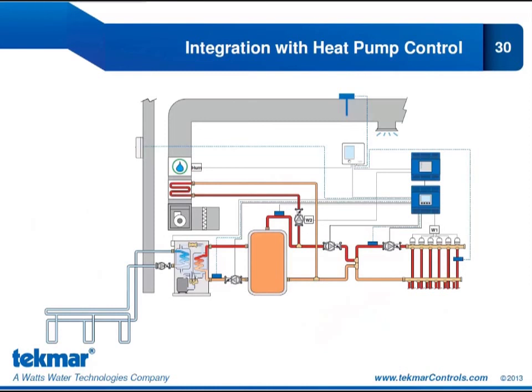Here's how the thermostat 557 might integrate with our house control 406 for an overall geothermal system. You can see here we have radiant floor, and that would be our first stage of heat. And it would also provide radiant floor cooling if we chose to design for that as well. Over on this other water temperature, we have our fan coil. So this fan coil, when we're in heating mode, would provide our second stage of heat. When we switch over to cooling mode, that fan coil would be our forced air cooling.